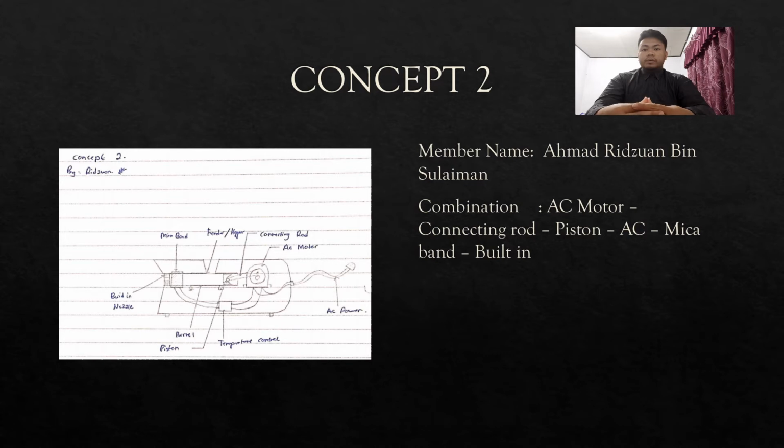How this concept works is we put the material in the hopper or feeder. Then the piston will move the material slowly, compressing the material into the nozzle to produce the filament.